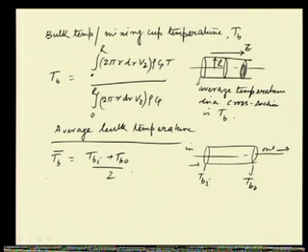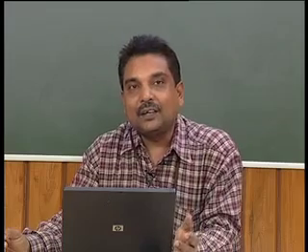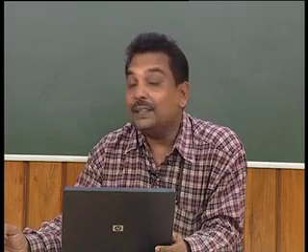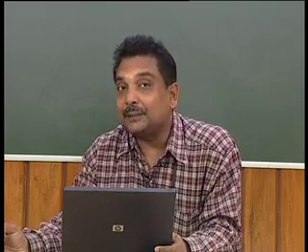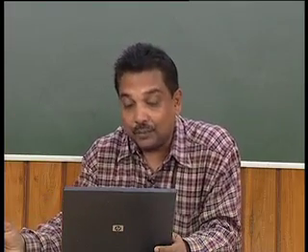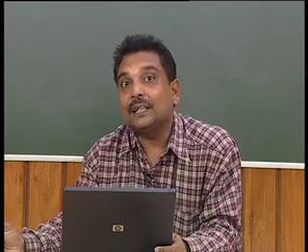Then another thing is wall temperature, that is also very important. Wall temperature we usually denote as T w. Wall temperature is the temperature of the wall, as we can understand from the name itself. Now, in many situations we may find that correlations are used for constant wall temperature, sometimes for constant wall flux. When there is a constant wall temperature, then T w is constant all throughout the surface, all throughout the wall, whereas when there is a constant wall flux, then T w may not be constant, T w can be a variable quantity.